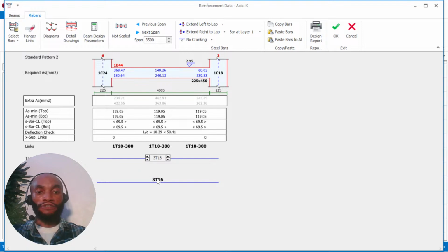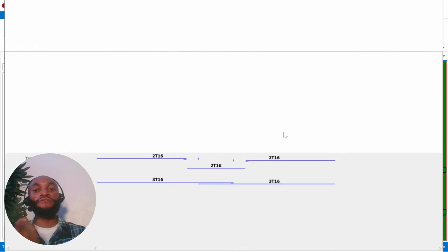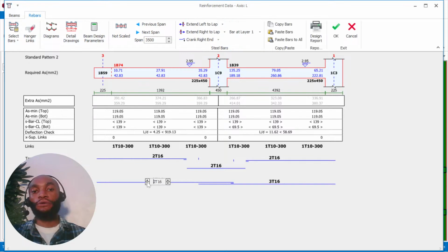And if I come here and try to reduce cost on this, you can see that this is okay. We're having 162 as the area of steel, and here we are moving to the place where the beams are failing, and you'll see how that will happen. So with this, I can choose to reduce cost because I can see that I have very high areas of steel here. So I'll reduce this to 2. You can see that it is still okay.